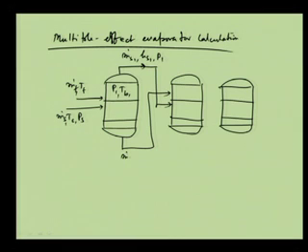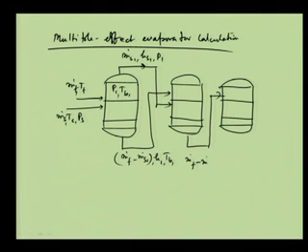So, this will be m dot f minus m dot S1, which is gone as a vapor. This much amount is going there, and it is having enthalpy H1, and Tb1 is the true boiling point of the concentrated solution. Similarly, here it will be m dot f minus m dot S1 minus m dot S2. So, this itself takes care of the mass balance, okay.